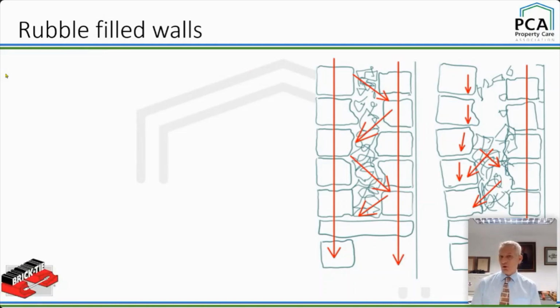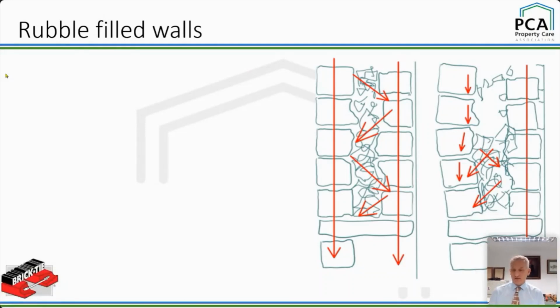The left-hand wall, typical rubble wall there. It's got a big giant cursor, hang on, here we are, yeah, big giant cursor. There's a through stone. A through stone being that stone which is longer and is turned on its end, so it spans the cavity and it bonds the two skins of masonry together. They don't both have to be stone. The outer one on the left there could be stone, the inner might be brick. It might be blooming rubble, it might be rubbish, you don't know.